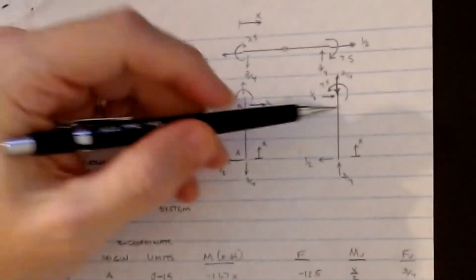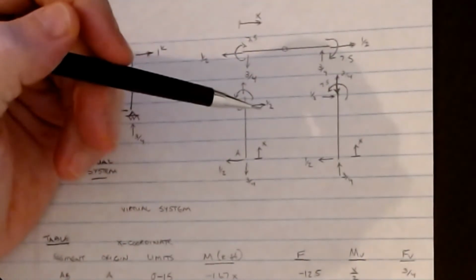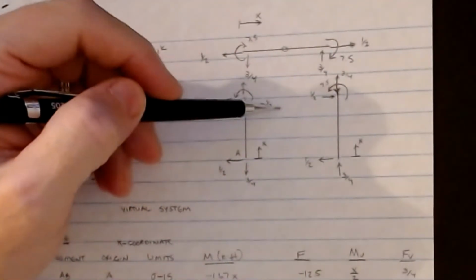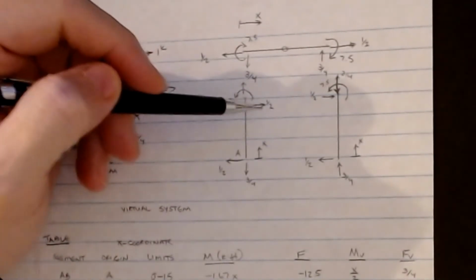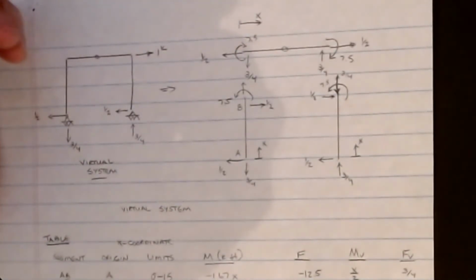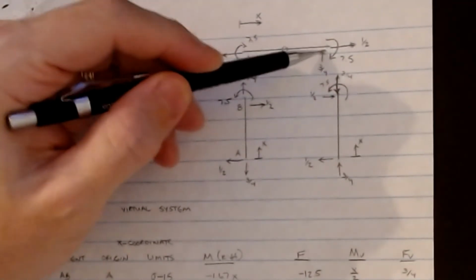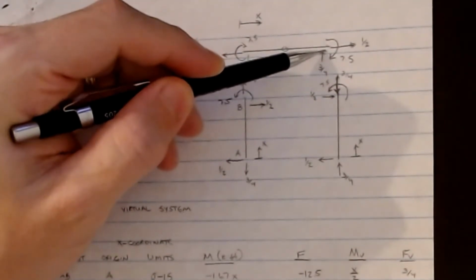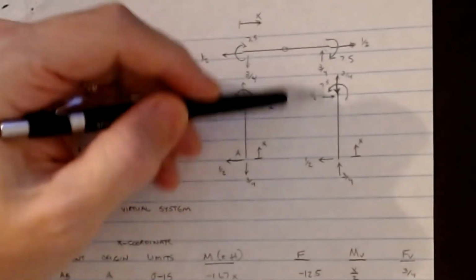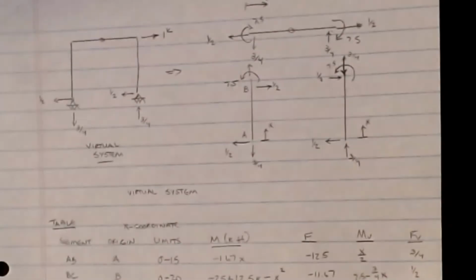All right, it gives me that 3/4, and then I get a moment of 7.5 at the top here, and then I get my reaction of 1.5 at the top there. Okay, and so that gets me all their pieces, and then those can go up and parlay into what's happening at the top on the beam. Okay, and again, everything here is opposite everything there, and everything here is opposite everything there on the sign. So you just got to watch the signs and be very, very careful.